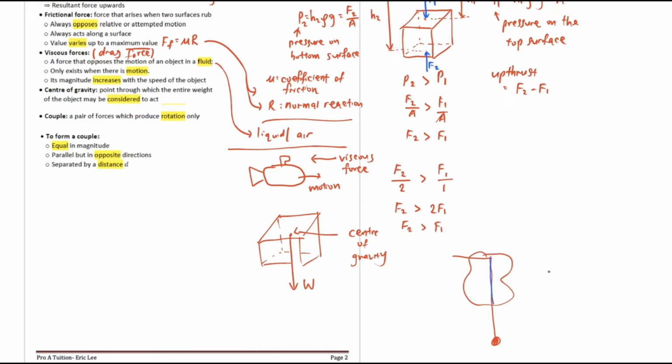Okay. Now you turn the object around. Let's say this same object, you turn it in this particular way. Just now you have the line already, this line. Now you do the same thing. You put a hole here, hang with a string, a pendulum and the bob here. Now you use your pencil to draw the line, following the string, and then you get the intersection point.